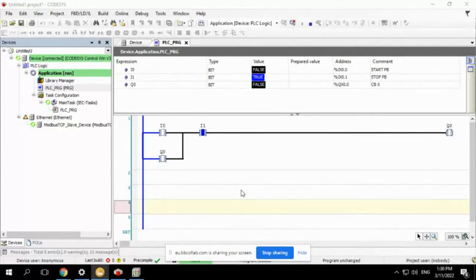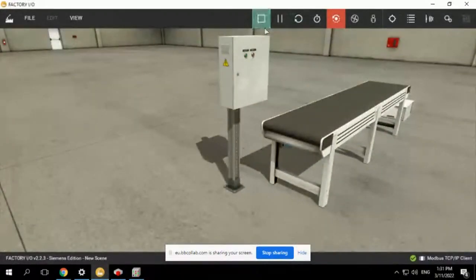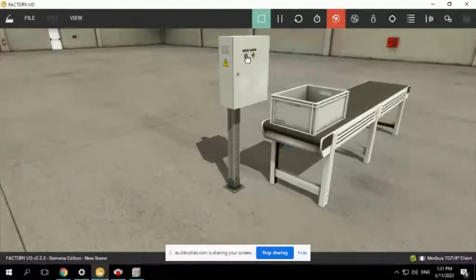Situation differs though. You will appreciate as I progress. But for now, for the basics of starting and stopping, this is how you use the normally closed stop button. And you will never find any stop button, whether the emergency stop button or the normal stop push button, as a normally open in this program, right?